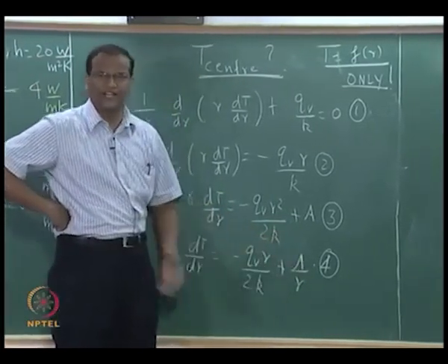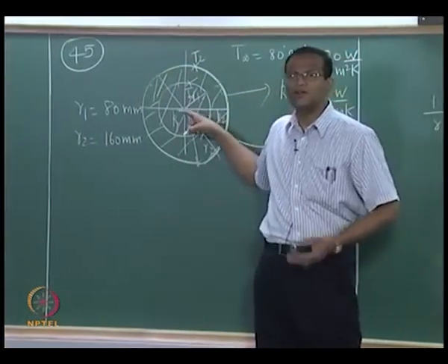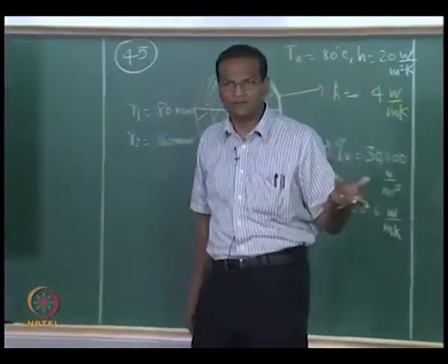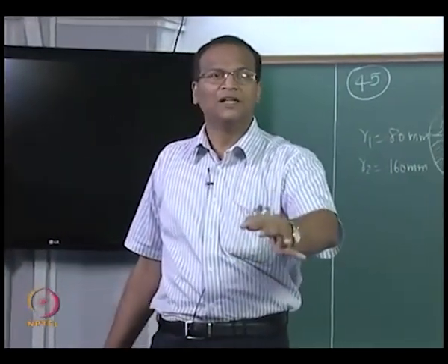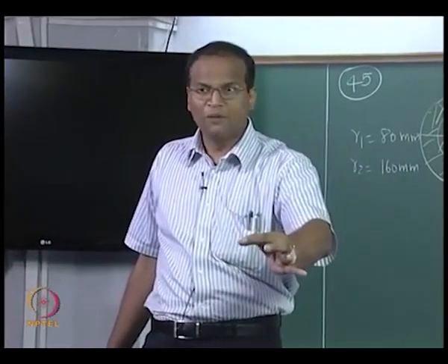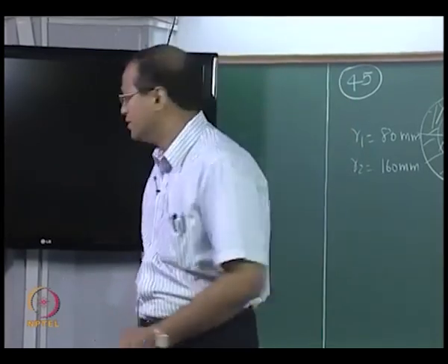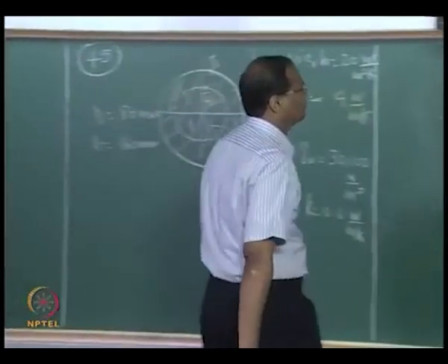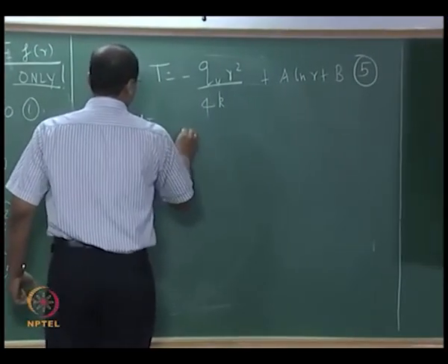This is called the finiteness of temperature, or you can say that any plane at R equal to 0 should be symmetric on either side of R. So the maximum temperature will occur at R equal to 0. That is where the area is becoming so small, the temperature will peak there. Okay. So dT by dR is equal to 0.